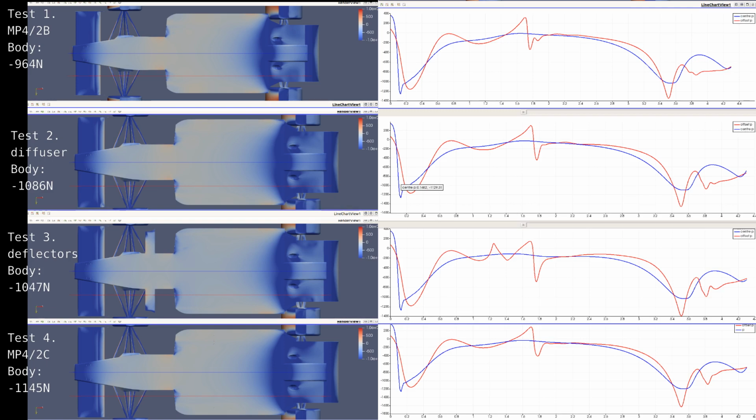I want to put the pressure plots from under the floor here because the floor is the place that is seeing the most change and has questions about the flow structure. As a complement to the pressure maps, the size of the puddles of blue equates to the lower pressure dips. A clue to the lack of effectiveness of the diffuser is seen in the red plot 400mm off the centre